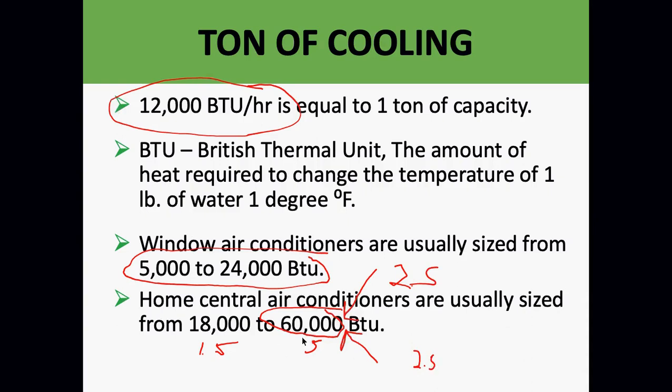Rather than having this big energy use running at one time, if I can put these in different parts of the house, maybe one on the south side, one on the north side, in terms of the air handlers and the space it cools, I might be able to get a little energy efficiency if I zone these by breaking this down to 2 units. Does that somewhat make sense?